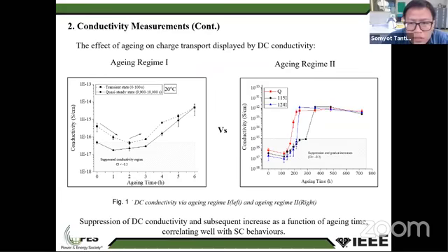And this is a conductivity comparison between non-uniform aging and uniform aging. You can see the same thing happen after the cable insulation is aged by temperature. From the reference here, when you have the aging process going on in your power cable installations, you could see firstly the conductivity will be reduced. That means you might think, when you test the cable, oh, conductivity is reduced, so this installation should be good.